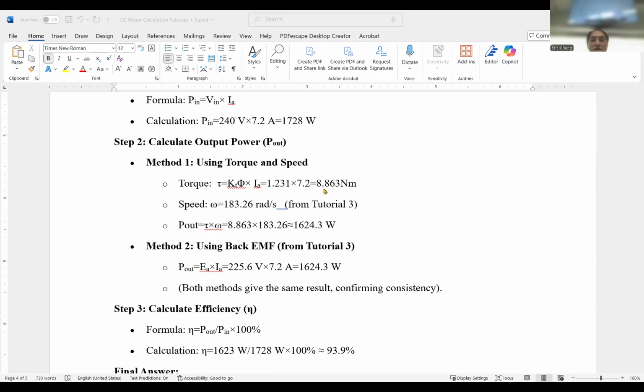So the next question is to calculate the speed and torque under PWM control. We have a separately excited DC motor with parameters RA and also the back EMF constant. You see the back EMF constant is in volts per unit radian per second. It's also controlled by PWM with a 300 volt DC source and 70% duty ratio.